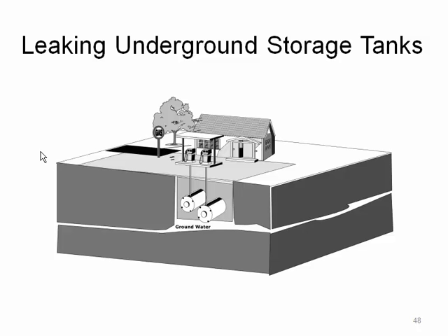This led to the advent of the modern environmental consulting industry, where companies formed and grew to oversee the cleanup and investigation of these sites. Since that time, there has been major improvements in the technology. Gasoline storage tanks underground now are double-walled and clad in fiberglass and other materials to reduce their corrosion. There are better leak detection monitoring systems and much greater emphasis on prevention of contamination of groundwater by gasoline, diesel fuel, sometimes oil storage tanks and things as such.